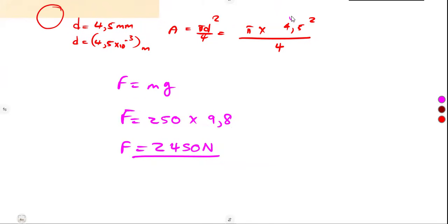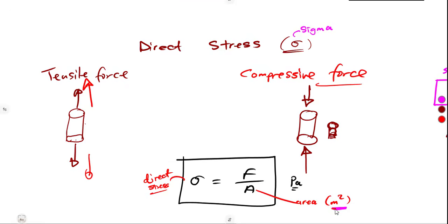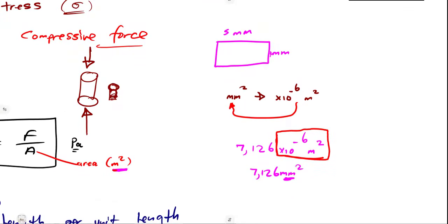So take note, this is in millimeters. So whatever answer I'm going to have will be in millimeters. That was going to give us something like 15,904 square millimeters. We are not supposed to be scared about the square millimeters, just because the area is needed in square meters. Why? Because we know the conversion between the two, from square millimeters to square meters.